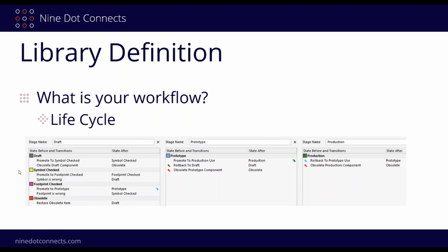In fact, if you think about it, in Altium Designer, the whole idea of a part choice is to take that burden off of you. That's why you put a part choice in there, because you can look at the part choice and it'll update in real time. And one of the other things it provides to you, by the way, is the status. It'll let you know whether or not it's got parts or not. It doesn't necessarily always give you the lifecycle status though.